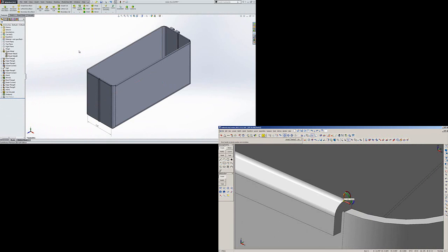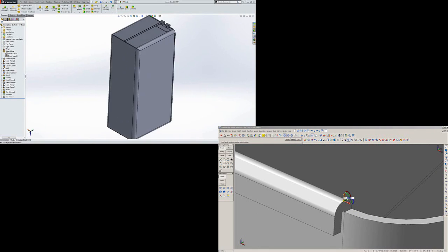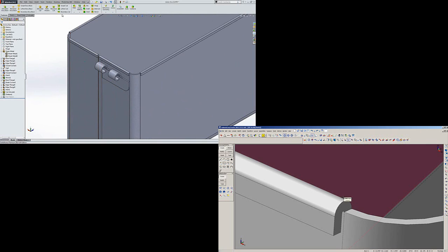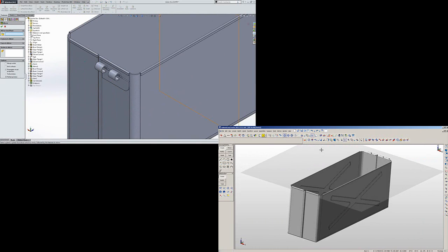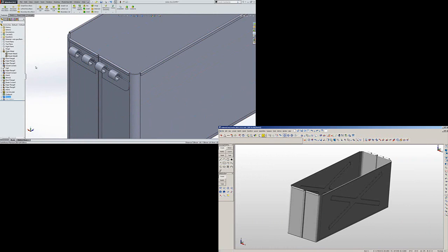And it's just down to us to now mirror that across to the opposing side. So I'm just going to rotate my model, wrong way, like so. Now I'm going to mirror about the right plane. Okay, and for the body to mirror, we're going to select this body, and we're not going to merge solids together. We're going to have another solid multi-bodied feature in our model.